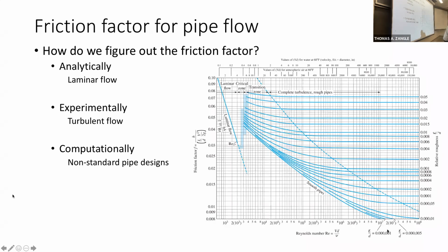So think of it as like the texture of the wall of the pipe. This table has a texture to it, probably a roughness of about 1 millimeter or so, that I can actually feel. And so if we have a flow inside of a pipe, which is really what we're concerning ourselves with in this chapter, then relative roughness is the roughness, the texture of that wall, divided by the diameter of the pipe itself, and that determines our third parameter.